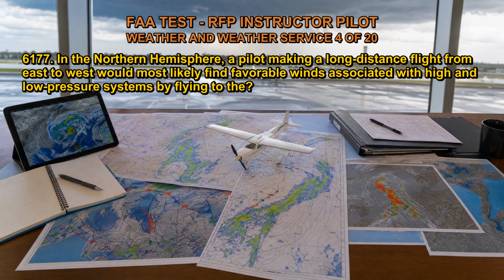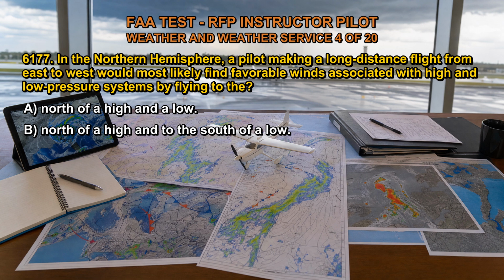6177. In the Northern Hemisphere, a pilot making a long-distance flight from east to west would most likely find favorable winds associated with high and low-pressure systems by flying to the: A. North of a high and a low. B. North of a high and to the south of a low. C. South of a high and to the north of a low.